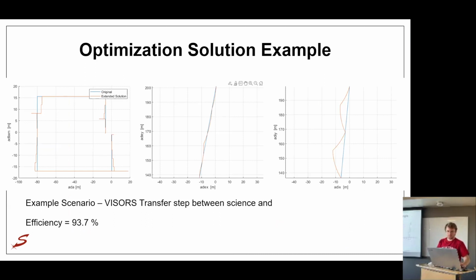The onboard solver we have is an interior point solver, not a simplex or a dedicated linear program solver. If you included a dedicated linear program solver, you'd probably have better checks of feasibility and get that faster than our solution. But this is already going on board, so it's a handy little addendum.